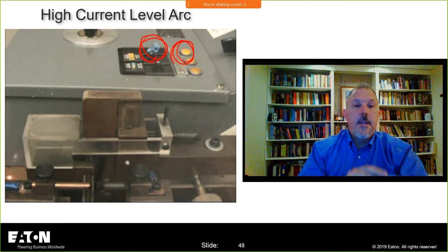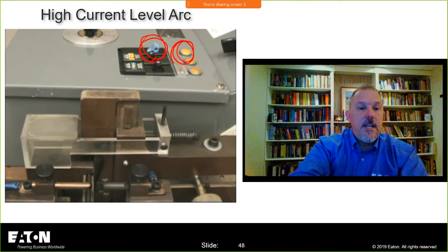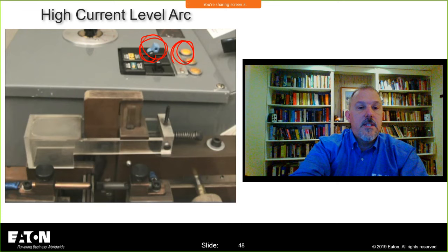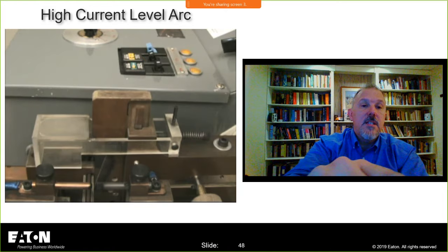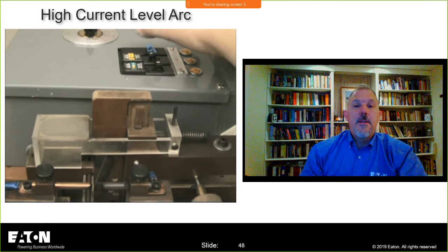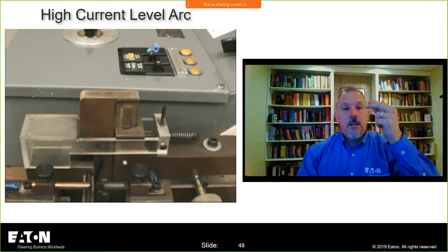Every time I turn on that breaker, the light is on. This is the SPT-2 cord down here going in, and this is the guillotine. That's the blade, and I'm teasing that circuit. That is what we call a parallel arc because I'm cutting across the conductor. It's a hot and a neutral.